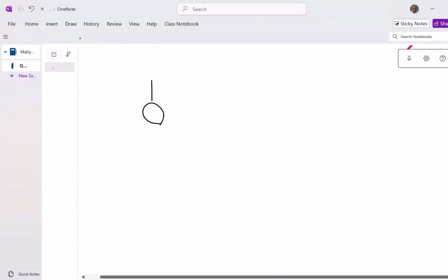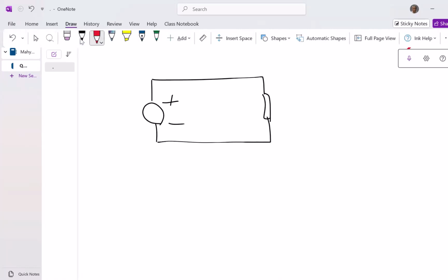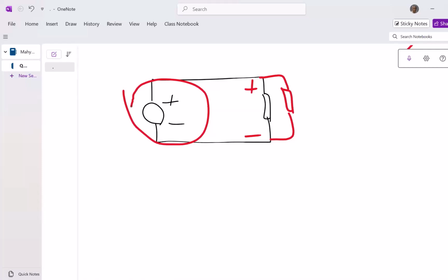This is the original problem. You had one load, one generator, and then we added the extra load. This voltage has dropped. Now you want the voltage to be back to the previous value. So you put the previous voltage back in here, recalculate EA.